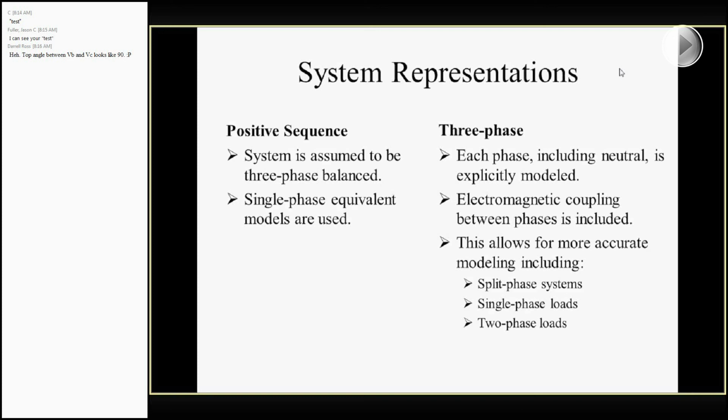This is used quite a bit in transmission systems, and it's a fairly valid assumption on that end of things, just because the system is operated fairly balanced. They do things like the line transposition and have their transformers in there appropriately to make sure the system is pretty much sending the same amount of current on phase A, B, and C of your power system.